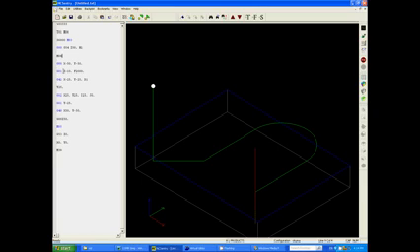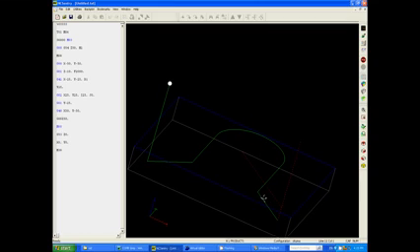Pretty simple. So now we're going to move back to a G0 move, and we're going to rapid to X -50, Y -50, which now you know that I only want to machine this profile here. So how come I'm coming in at an angle like this and leaving at an angle as well?